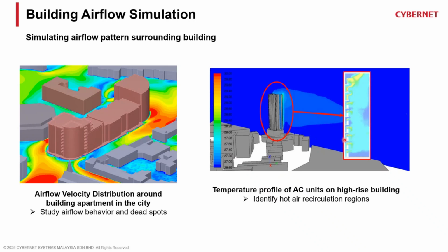Then eventually, once the ambient temperature is raised enough, let's say over the critical temperature, say 42 degrees, it's going to cause the performance of the unit to go down, and sometimes even shut down as well. So in that case it's not ideal, because you will feel that your aircon inside the room is not really pumping enough cold air. This is basically because your outdoor unit is not performing at the optimal condition.